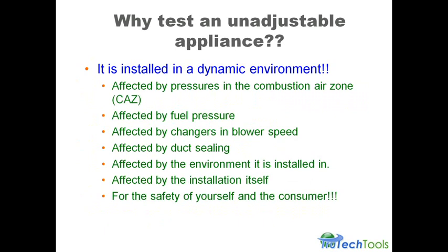You kick on the dryer, that could affect the furnace. It's affected by the fuel pressure. It's affected by changes in the blower speed. A blower speed goes from high to low. You have a variable speed blower in the house. You have a modulating furnace. The blower speed's ramping up. You got some duct leakage maybe.